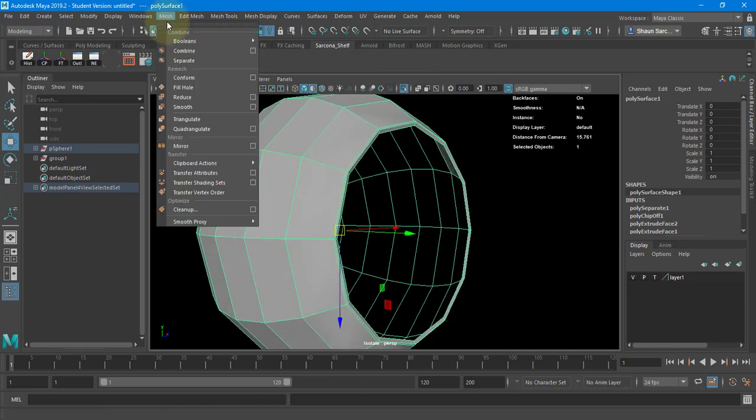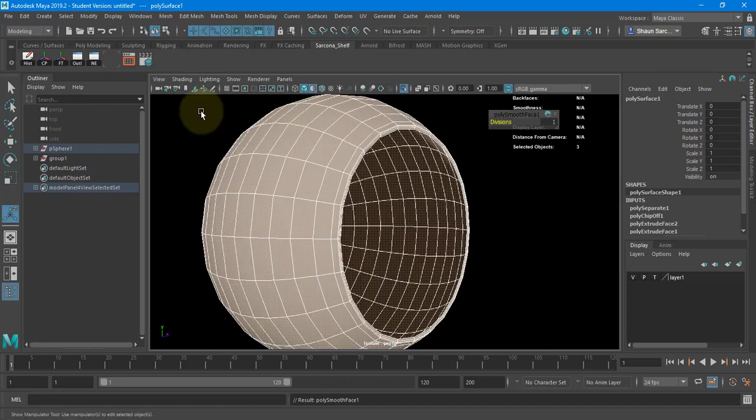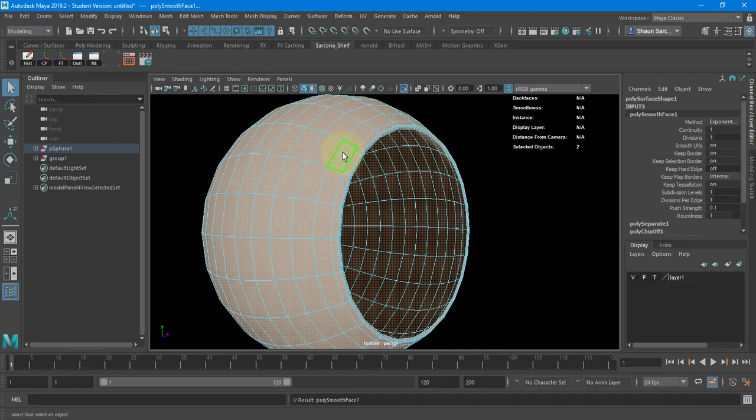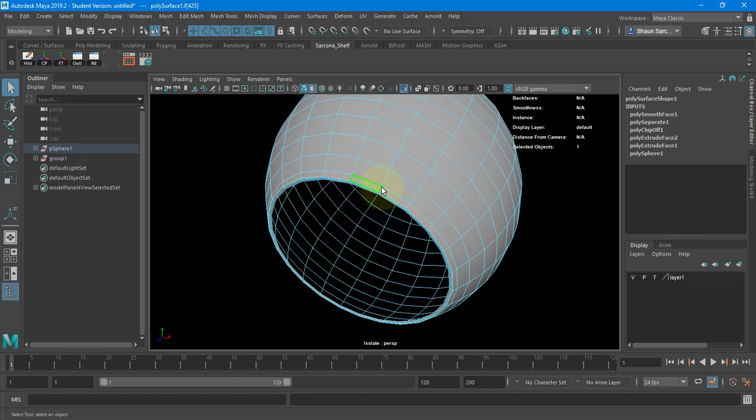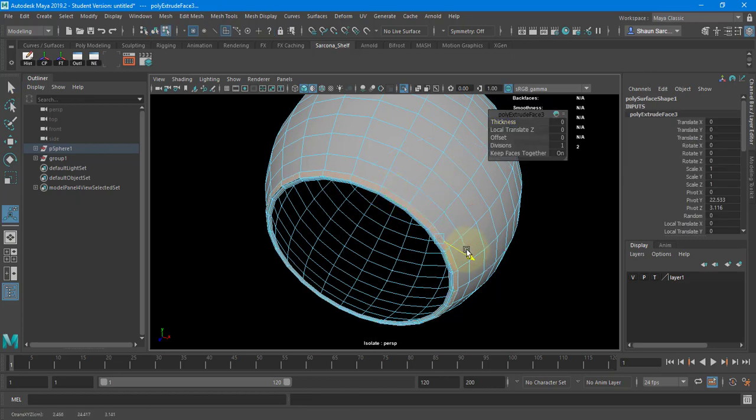It's not going to be a whole lot of details, grooves and whatever else like that. So I'm going to smooth it, so I actually get a smoothed out version, a lot more rims here. And then I'm going to go to my faces, and I'm going to grab this one, that one. And notice how I clicked here, held shift, and then double clicked the next one. It loops it around, okay? And I'm going to extrude that out.